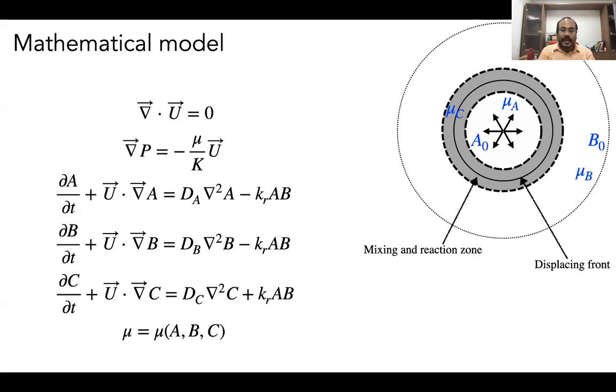And capital K is the permeability of this medium, which tells how easily the fluid can permeate through the porous media. So when we talk about porous media, we can always think of a kitchen sponge or wood, in which the fluid basically seeps through it. How easily the fluids can seep through it is given by the permeability of the medium. So that's the property of the medium, and the viscosity is the property of the fluid. So both sit in this proportionality constant.